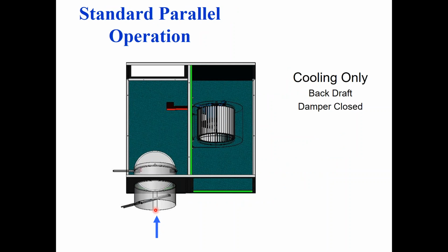This is what it's going to look like for him. So in this case, I still have my 55-degree air inlet. I still have my plenum inlet, but instead of the fan being over here on the discharge side, he's over here in parallel with the primary air, and he just pulls plenum air in as my first stage of heat. So if I have a heating call, I'm already going to back my damper down to some minimum ventilation position, because before I get a heating call, I should be having requests for less and less cooling. So this damper on the left is going to already throttle back to whatever his minimum position is.